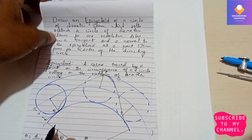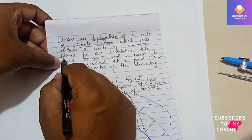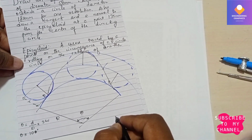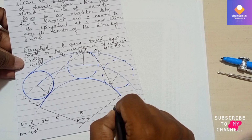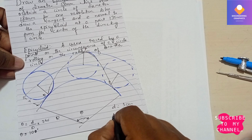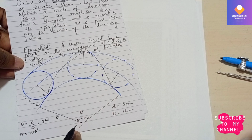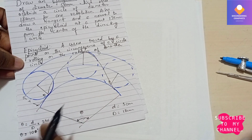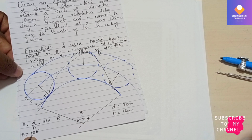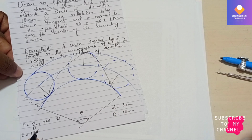As per this question, we have two circles, one of diameter 50, another of diameter 180. So we have two diameters: small d is 50 mm, and capital D is 180 mm. If I am drawing the bigger circle, we have to find out an angle, for how much I have to take. For that we consider theta. Theta is equal to small d by capital D into 360 degrees. If we substitute the values, the angle we get is 100 degrees.